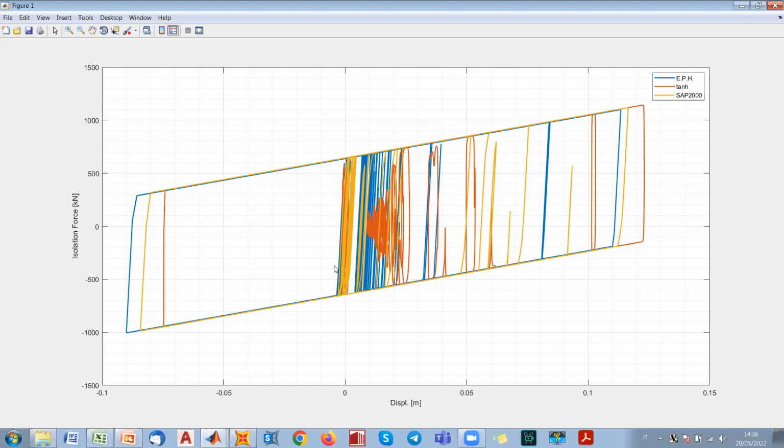So you see that according to the maximum displacement, we have a very close one, which is this one at this location. We have the maximum deformation. So we have actually the closest results, which is related to the elastoplastic behavior with hardening, you see. And the overall response is fairly represented also by the single degree of freedom oscillators. We have exactly the same force response and the same global behavior. Let's say we have different branches, but actually this is just related to the hysteretic response.